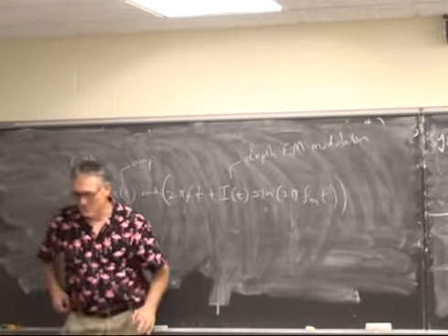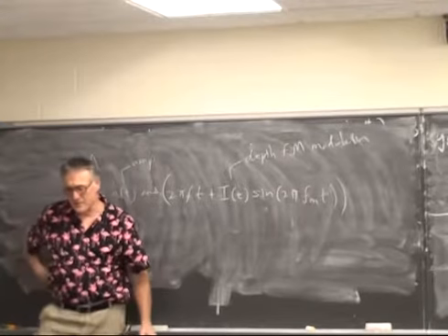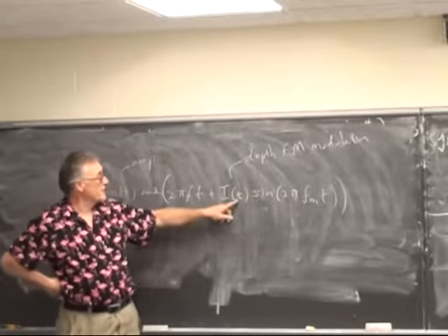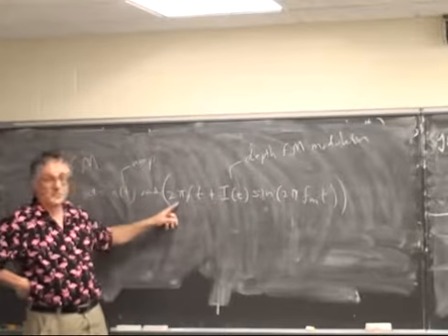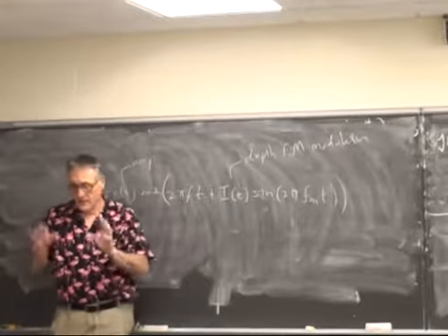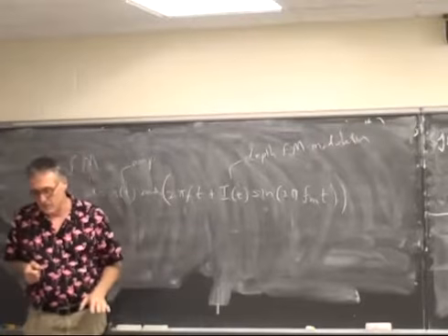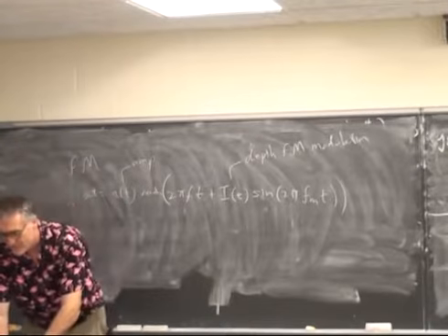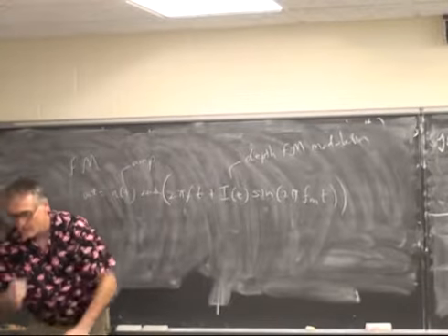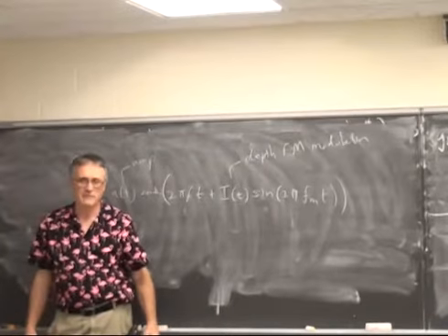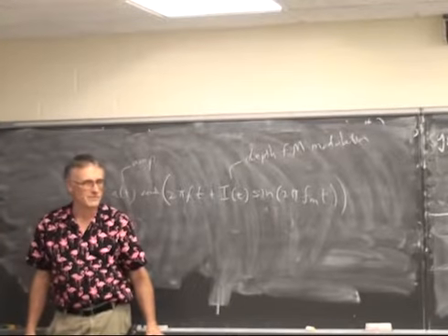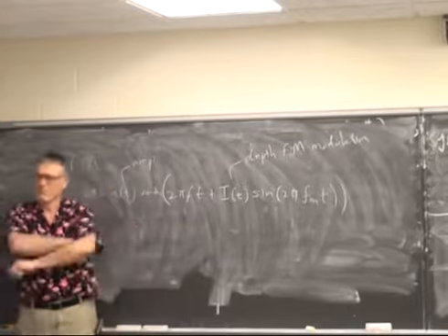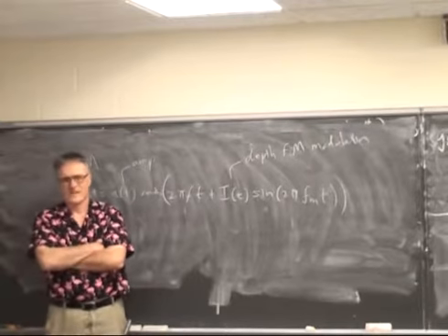Yeah, there's some weird overtones there. The main frequency there is set to 300, and the FM frequency is set to 1,000. So the phase here is changing 3 times as fast as the phase here, and you're getting all kinds of weird interferences between the two. Depth is pretty high. How about this? Kind of indistinct.